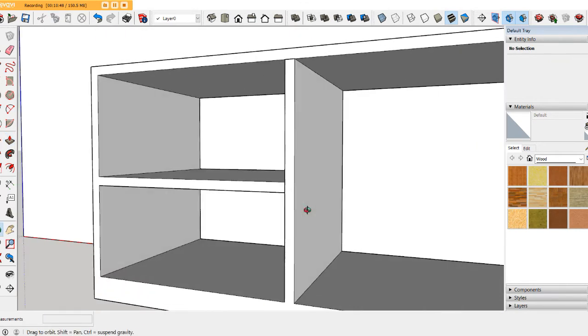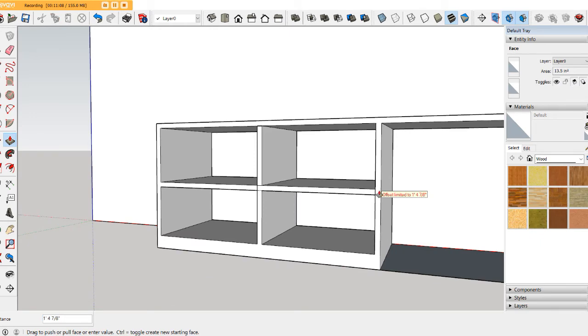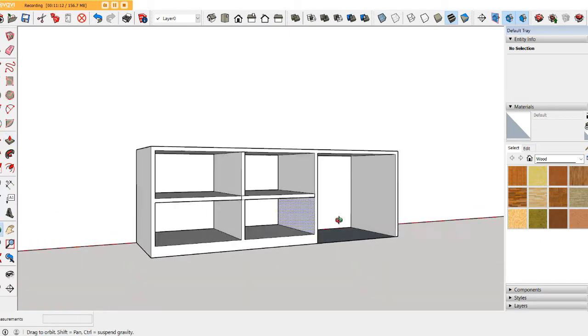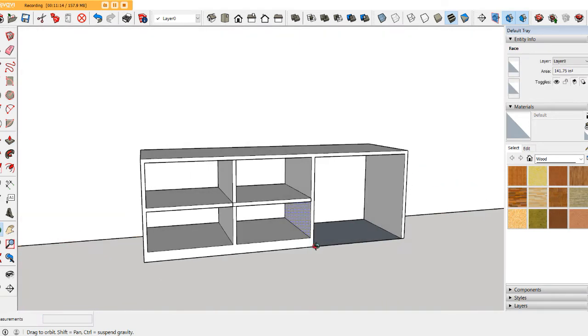So extend it until the edge. Okay, likewise, now what I will do is to draw another two lines. I will just copy these lines here so that they will be used as guides for me, and click them until here. Okay, and then I will be using the pull command to bring them also up to here. Okay, so that's how it's done.